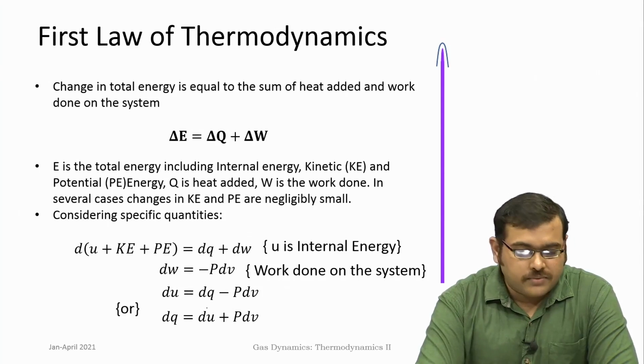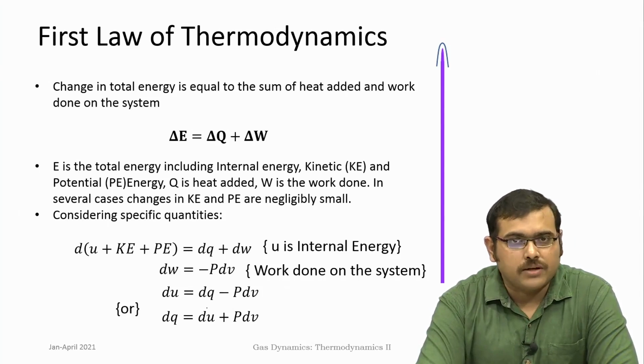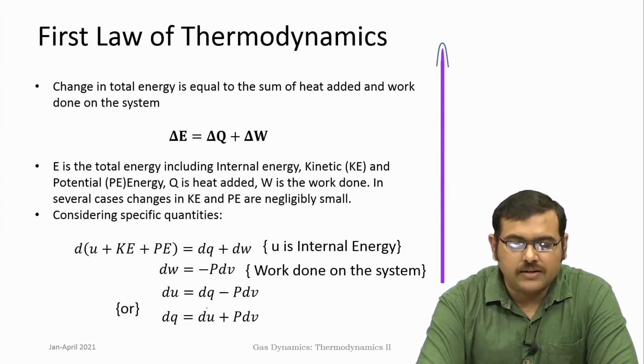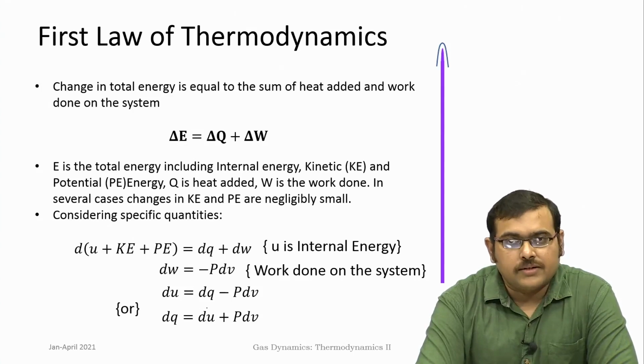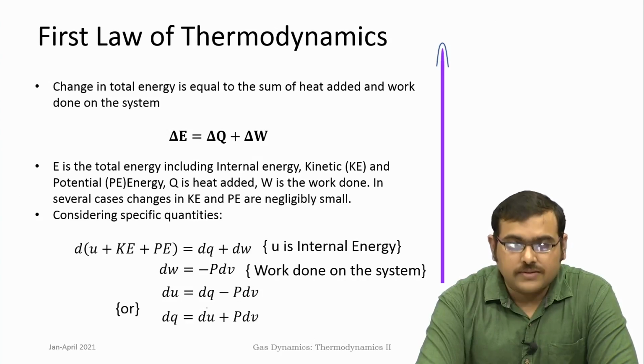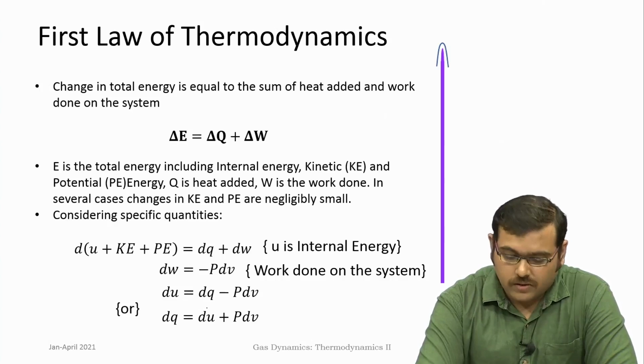The energy that we are considering includes internal energy, kinetic energy, potential energy, and in many cases these changes to the potential energy and kinetic energy can be quite small. Then when you look at the change in energy, essentially you are looking at a change in internal energy, and work done on the system is the PdV work, which has a negative sign corresponding to the sign convention. This is the work done on the system.